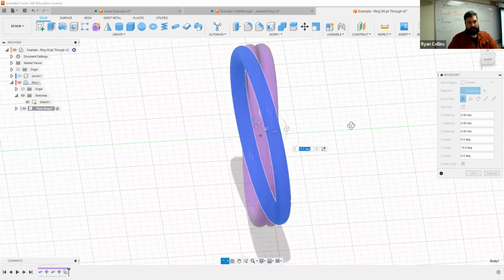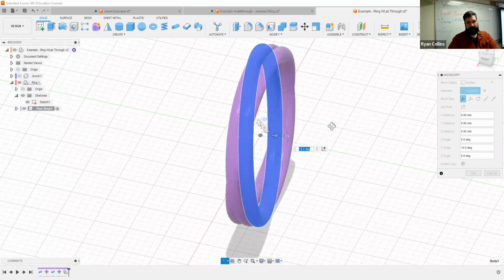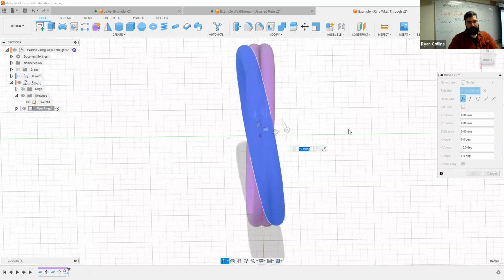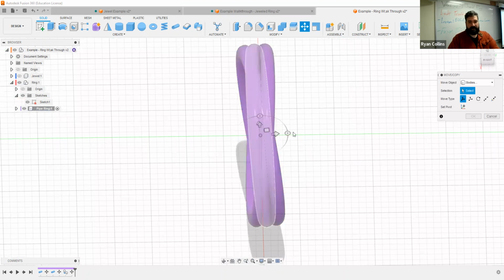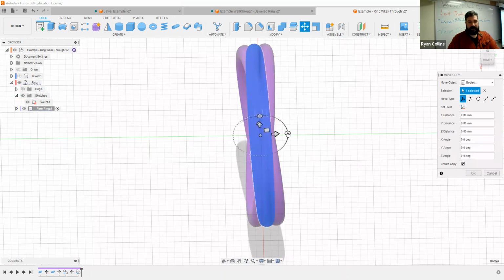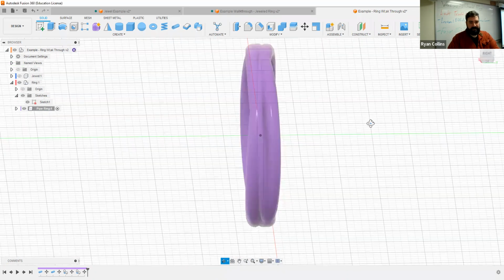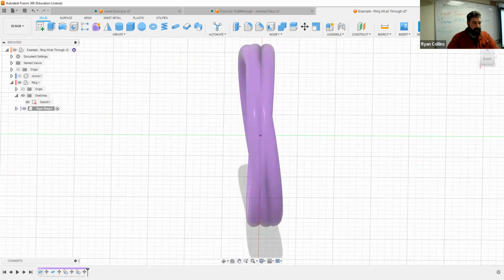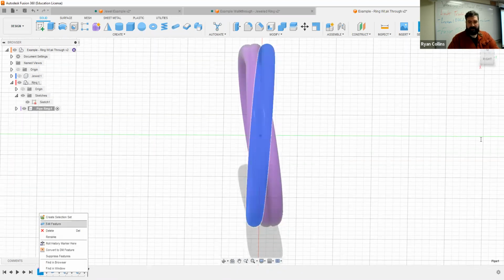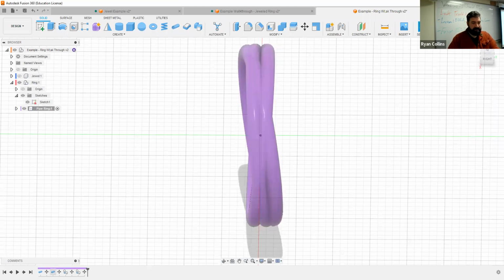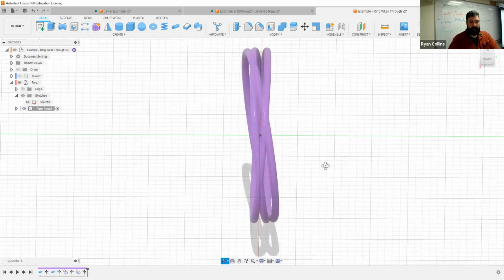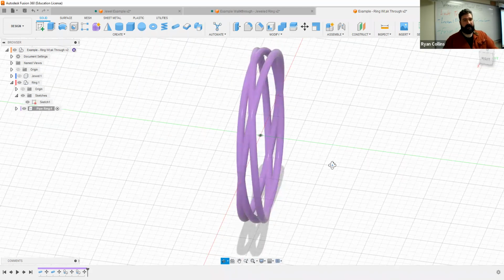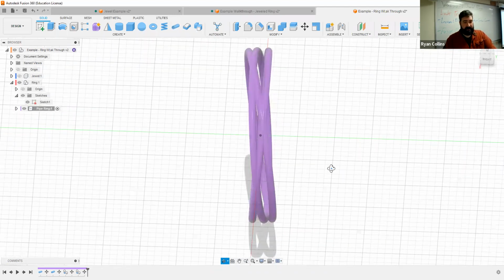I don't really like that. Or do I? We'll do 10 degrees. Great. Made a copy. Do it again. Off the original one. Make copy. Rotate the other way. 10 degrees. There you go. So kind of turning into this horrible mass, but what we could, of course, do is just go back. Instead of a 2 millimeter, let's make that 1. Do the same since I made the original copy there. Let's make that one selection, that section size 1 millimeter. There we go. So you can see you can start creating these interlocking rings, or they're not interlocking, they're legitimately overlapping.